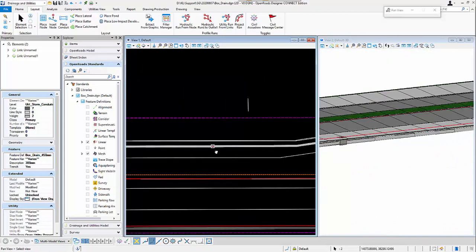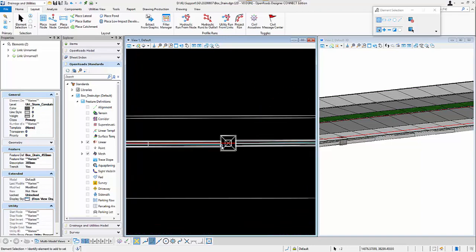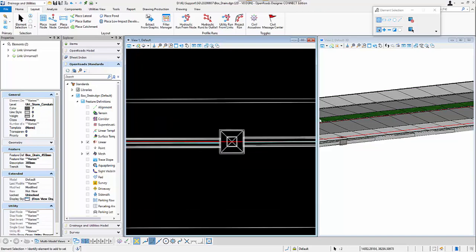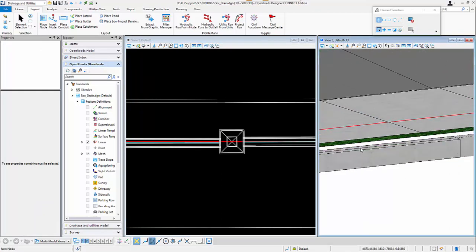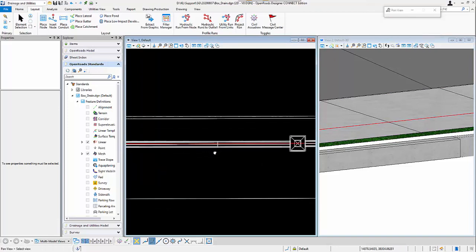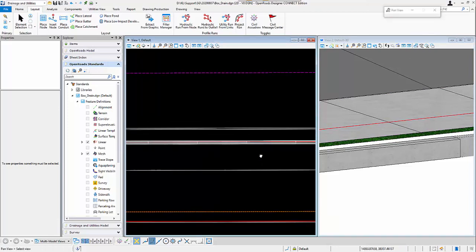The last step is to apply the point control to the GL point in my template. Remember, I just showed you in the template dialog, it is the top level, the top of my slab for my box string in the template. I will assign it to this linear element, the geometry element, so that the top of the slab approaches the corridor surface by using this linear element.